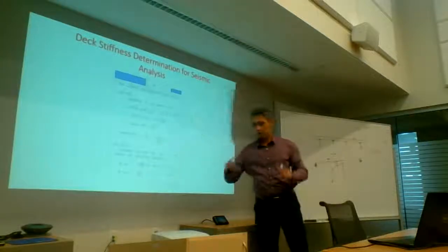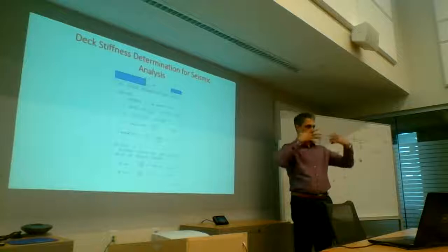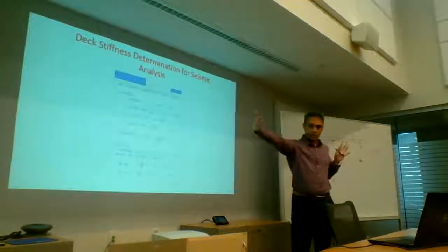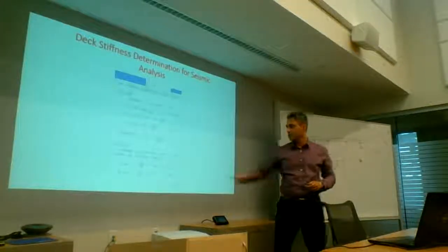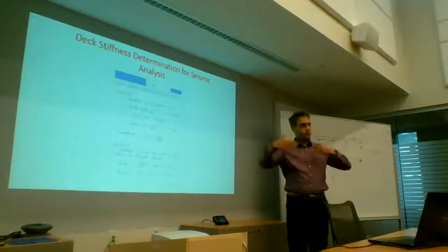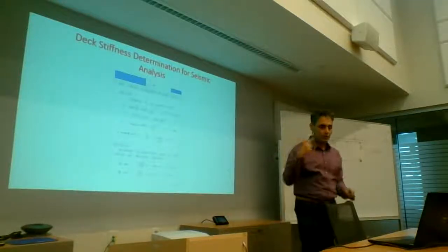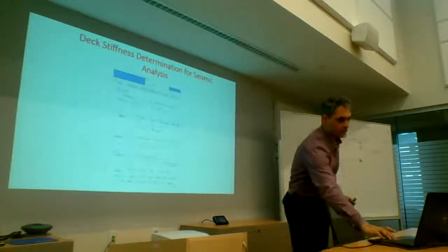For horizontal, you're reducing the vertical dimension, right? Because that doesn't impact this way. It's this width that's going to impact. So now you divide the 225 by 7.4, and now this is a deck which is 10.98 wide, but only 30 mm thick.